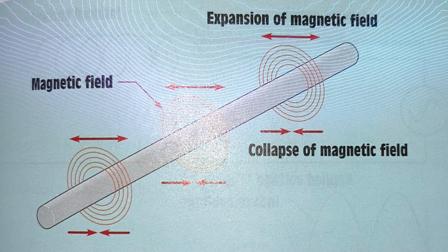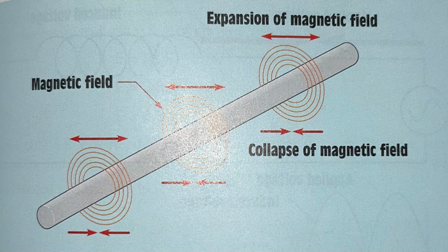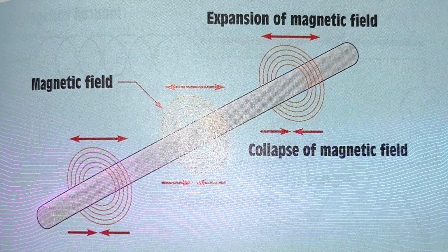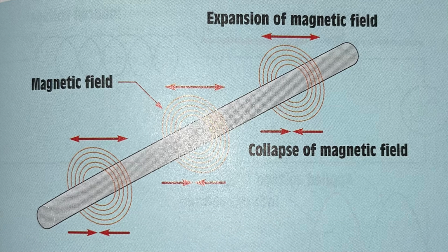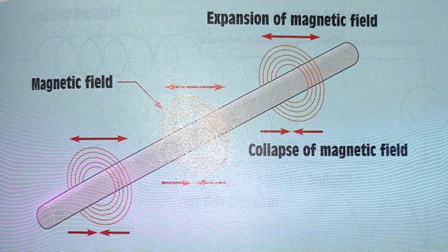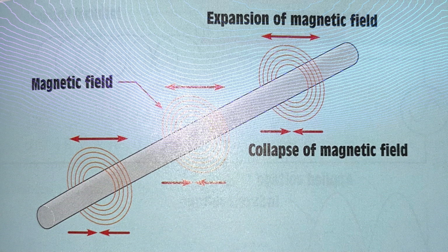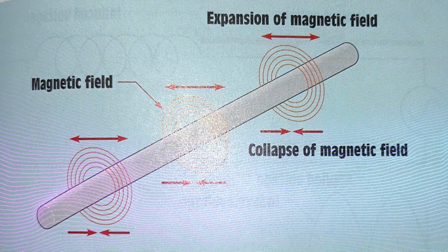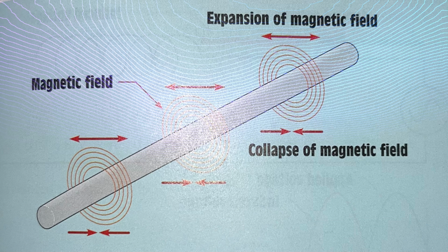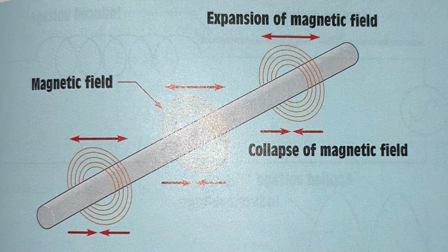In a pure inductive circuit, the current lags the voltage by 90 degrees. At first, this may seem to be an impossible condition until the relationship of the applied voltage and induced voltage is considered. How the current and applied voltage can become 90 degrees out of phase with each other can be best explained by comparing the relationship of the current and induced voltage.